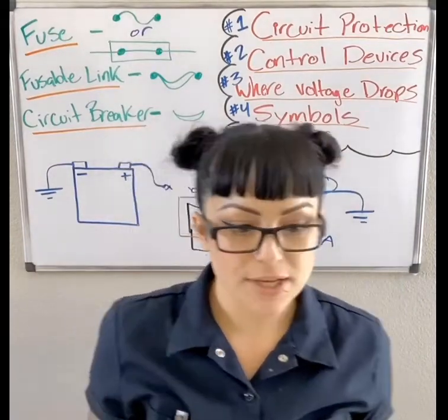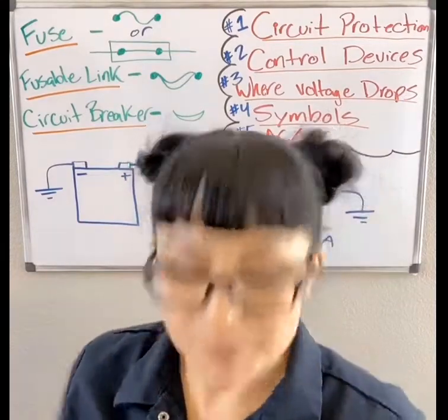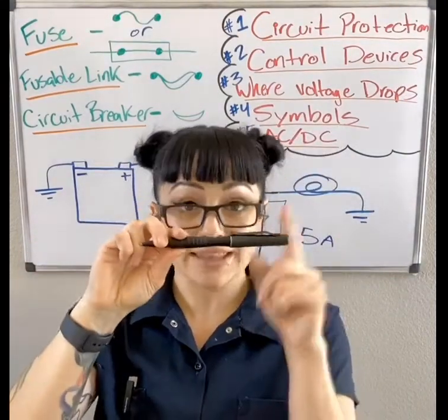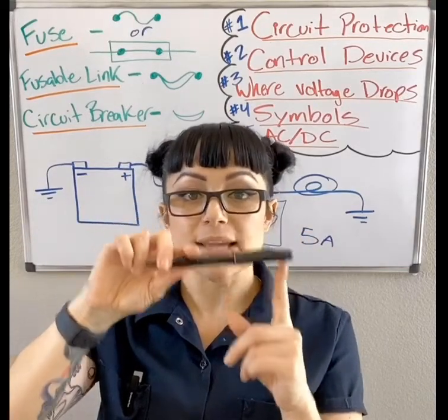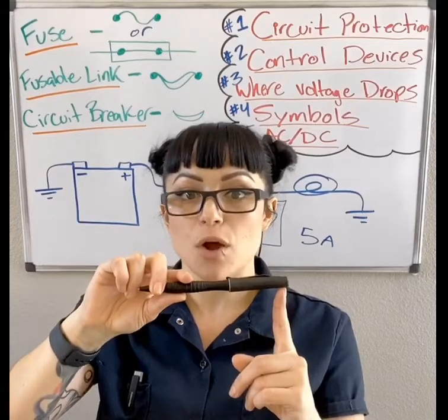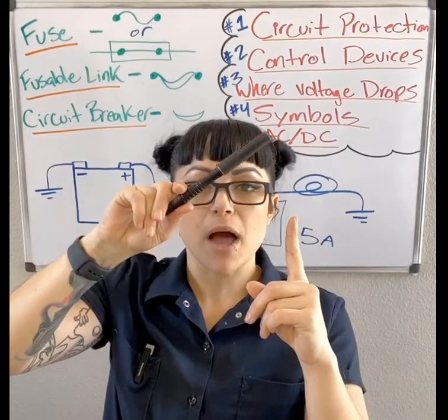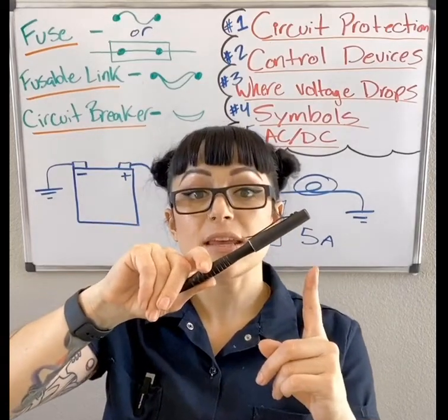Let me use something a little bit stronger. So let's say we're making a contact here from inlet to outlet in our circuit, and we get a temperature spike because the amperage flow is too much. What will happen is this will warp up because of the heat, and it will disconnect the connection.